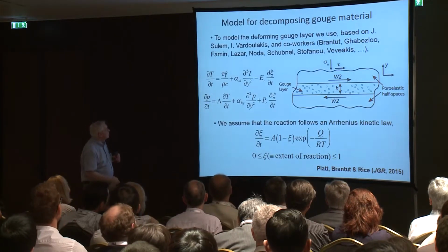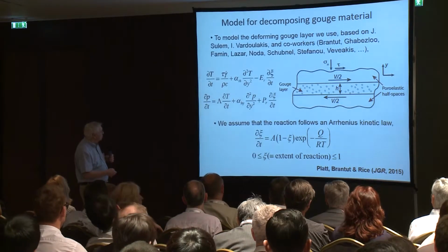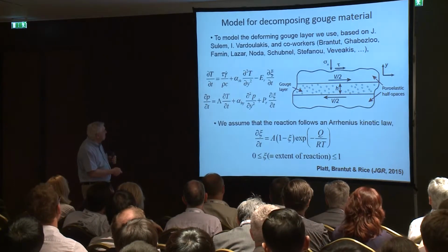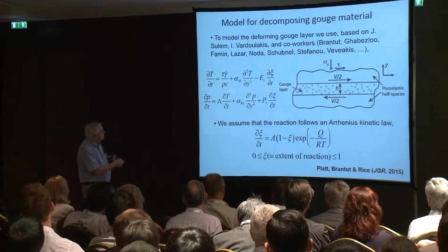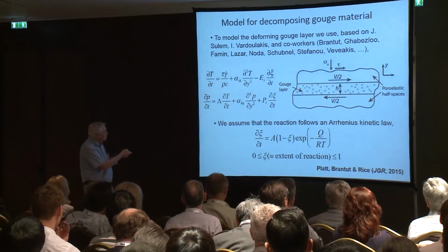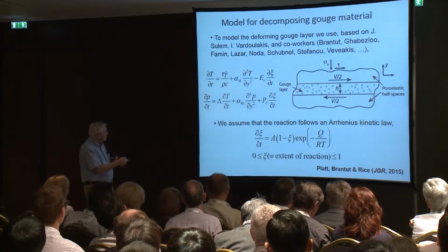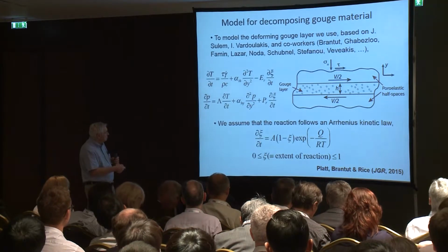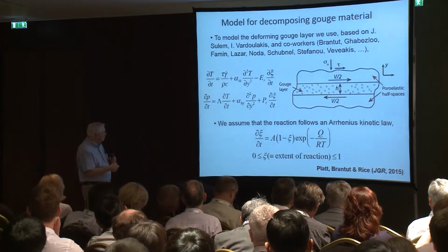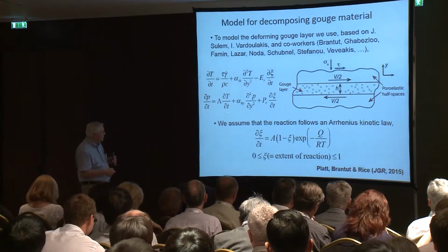So naturally, we, being modelers, like to make calculations of what would be implied by the things seen in such experiments. So we set up the equations, as you see here, a heat or energy conservation equation, the top line here, and then the next line is a fluid mass conservation. We recognize, of course, that that comes down to an equation for pore pressure once we relate fluid density to pore pressure and temperature.